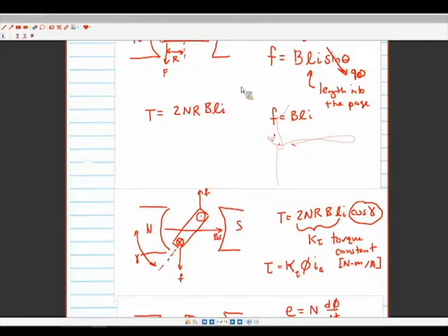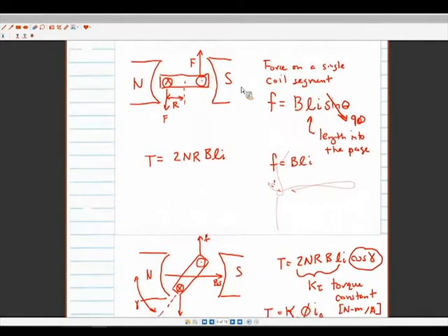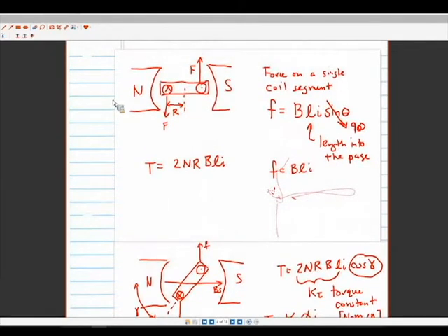That's the maximum torque configuration. So cosine gamma is going to be typically around a value of 1 then, because of commutation. We're continually switching what coil is activated. So most of the time we're looking at a situation where it's in this configuration at the top here. By the time it rotates appreciably far from that, it switches which coil is active.